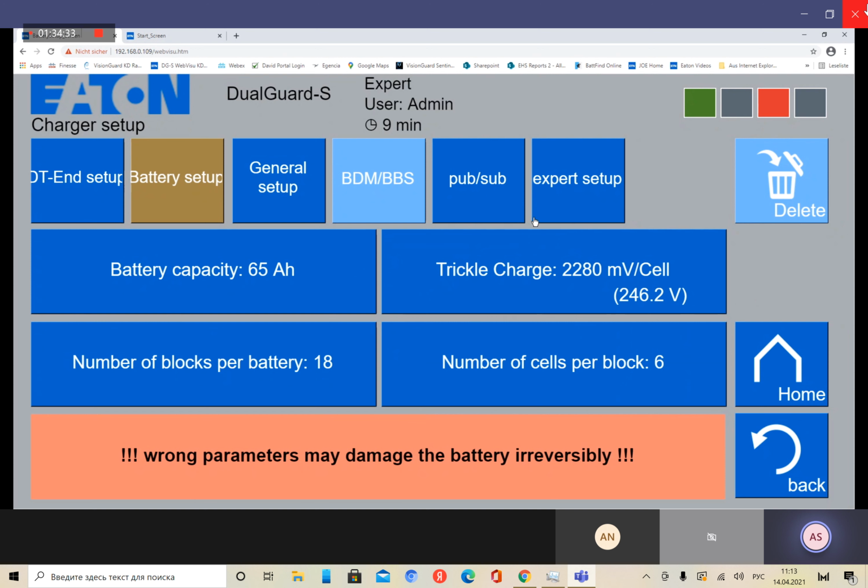After you did this, don't go to the BCM module and change the trickle charge on the BCM module manually with the BCM service pin, because this would cause you to have different parameters in the menu than the BCM is really providing to the batteries, right?